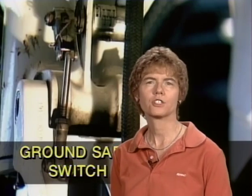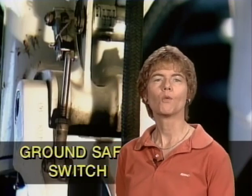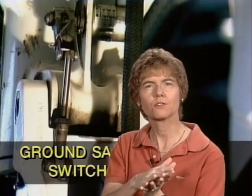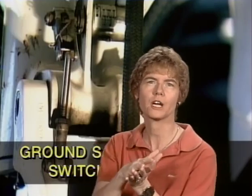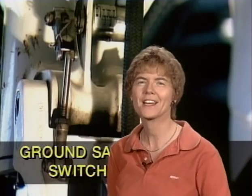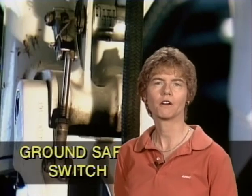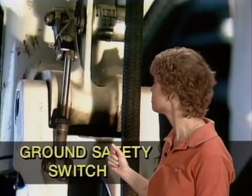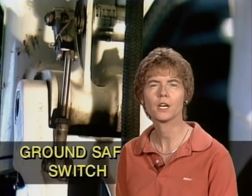It's got a lot of functions, but one of the functions is to avoid accidentally retracting the gear when you're on the ground, because what it will do is when that strut compresses and activates that switch and says, okay, there is weight on the aircraft, and I know there's weight on it because the strut has compressed and it's activated this ground safety switch, it will not let you, theoretically anyway, raise the landing gear, because it says, hey, I'm on the ground, I don't want the gear up. And then after you take off and the strut extends, then you will be able to retract the gear, because that ground safety switch says, hey, I know you're airborne, that's okay for you to go ahead and do now.